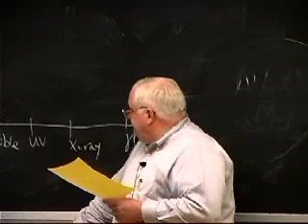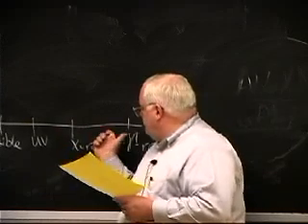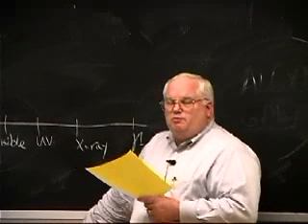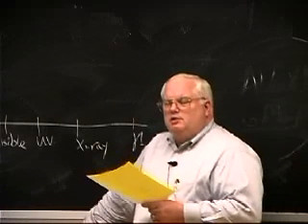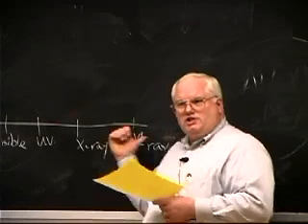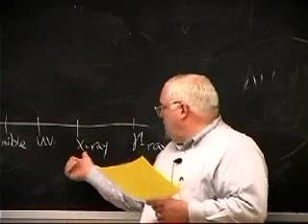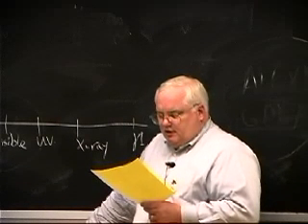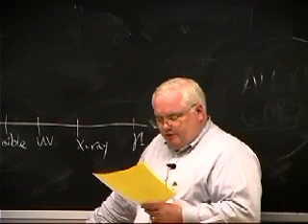Anyway, of course, X-rays and gamma rays: we actually use radioisotope sources, iridium 192, cobalt 60. They're using gamma rays from nuclear decay. We also use high voltage X-ray generators to penetrate steel and aluminum and things like that.